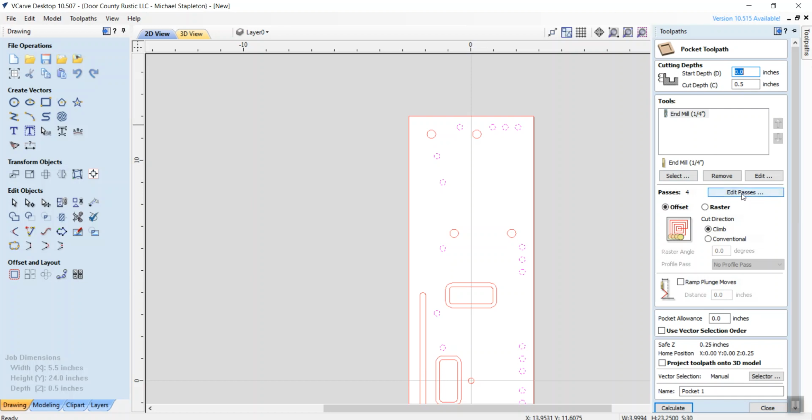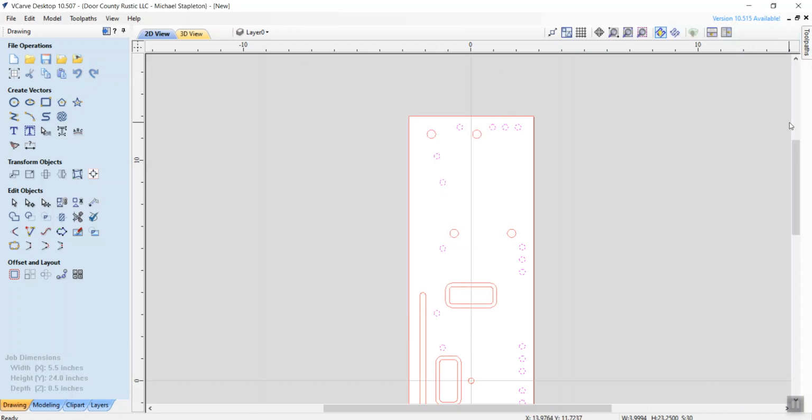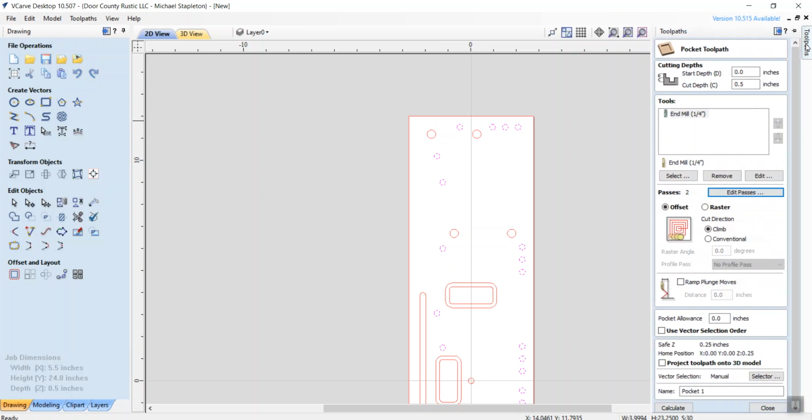And again, these are all 1/4 inch holes with a 1/4 inch up spiral full carbide bit, so I'm comfortable converting that to 2 passes on each of those. So I converted it to 2. I say okay. Again, it did the auto hide on me. I don't know, jury's out on that one. I'm going to name these, and this would be all 1/4 inch holes